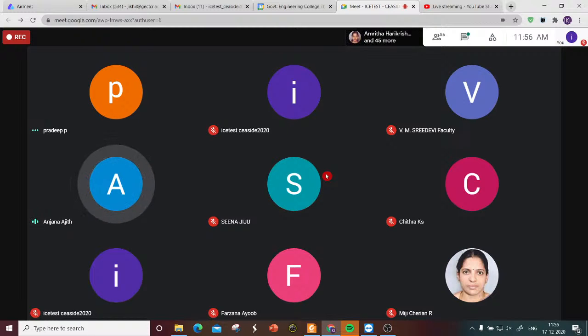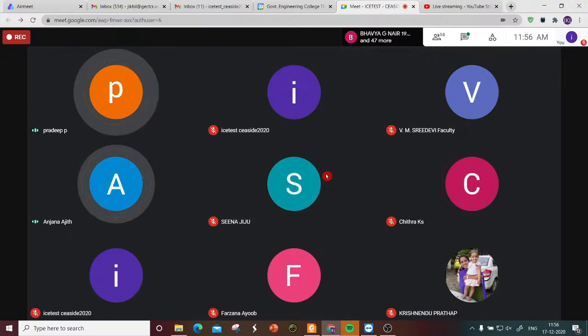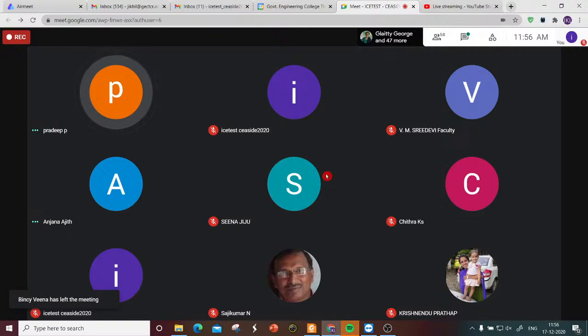Is it available in that form? Yes, it is available in the pelletized aggregate form only. Nearly rounded shape, porous, also lightweight. Then what do you mean by pre-soaking? Pre-soaking means before mixing with the concrete, it is soaked for about 2 hours to ensure about 12% absorption, so that the mixing water is not absorbed by this porous aggregate. So we soak it prior to mixing for about 2 hours.